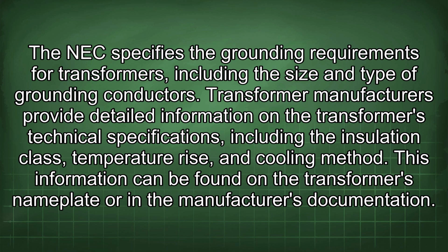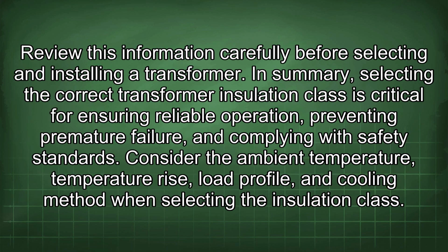Transformer manufacturers provide detailed information on the transformer's technical specifications, including the insulation class, temperature rise, and cooling method. This information can be found on the transformer's nameplate or in the manufacturer's documentation. Review this information carefully before selecting and installing a transformer.